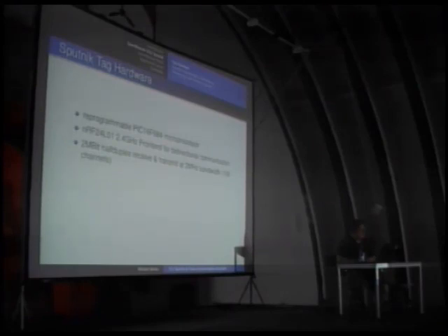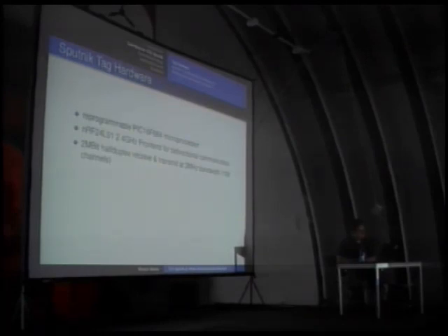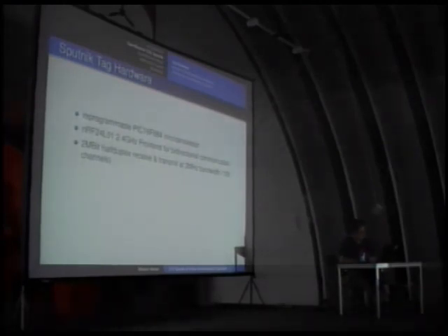It provides a FIFO up to 3 packets. It decodes automatically MAC addresses. It checks CRCs. You can save insane amounts of power by just clocking in the data, turning your processor off, and the NRF chip will handle everything autonomously.